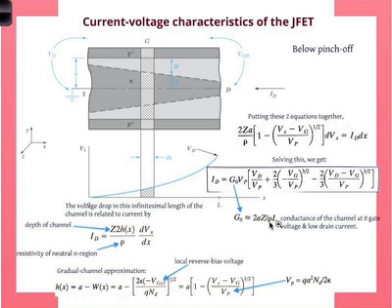Look at the rho. That's the thing which will change. The resistance of the channel, we assumed, is a material property, independent of the field. But if the mobility actually changes with the field, we know that the resistance has to change. The resistance is related to mobility. Remember, mobility depends on scattering, and that's what gives rise to resistance in a semiconductor. Remember where resistance in a semiconductor comes from. Okay, so that's the idea.